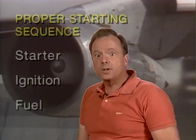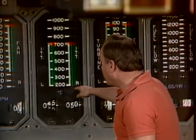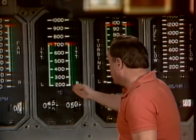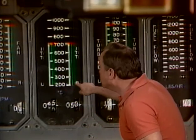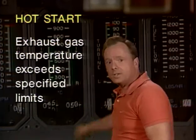Now, what is a hot start? Well, a hot start is if you have exhaust gas temperature go too high. How do you tell when you've started an engine? Well, the first indication of starting an engine is a rise in the ITT or exhaust gas temperature, either one. So a successful start is indicated by the rise in the ITT. If the ITT or exhaust gas temperature goes too far, then you have a hot start. According to the FAA, if exhaust gas temperature exceeds specified limits, that's a hot start.